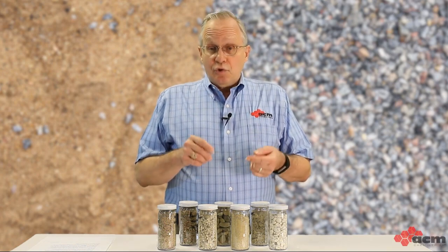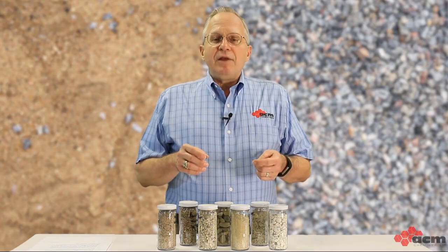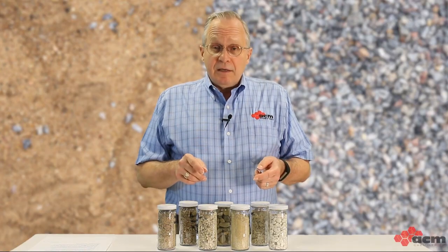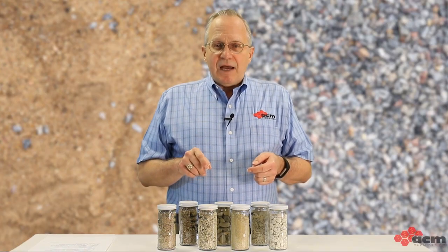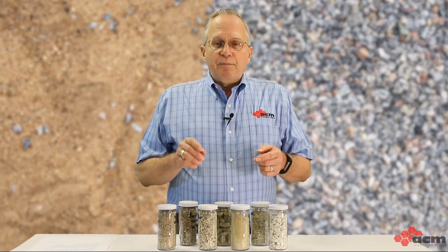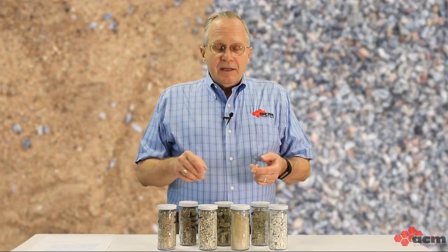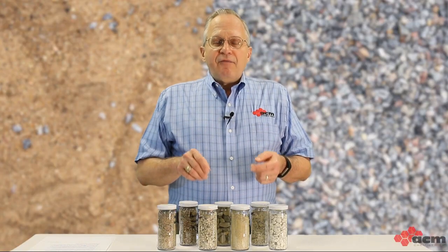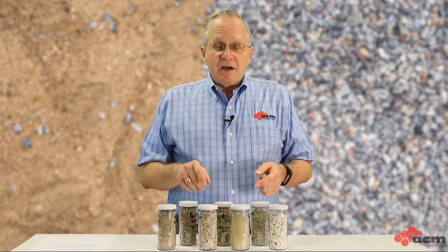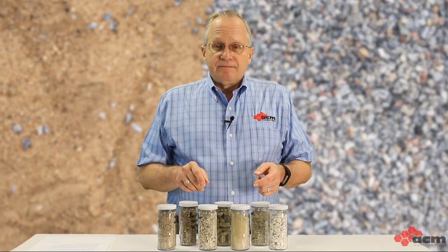Then we blend two or more aggregates together to get good particle packing, which means that all the aggregates fit well together. To get an optimized blend, we choose just the right amount of each aggregate so the overall blend fits our target curve. For pavers, the target curve is an M curve with a coarser peak that helps drive the mix into a mold and a finer peak for filling in around the coarser particles. This maximizes our concrete density and gives us improved performance at the lowest cost.